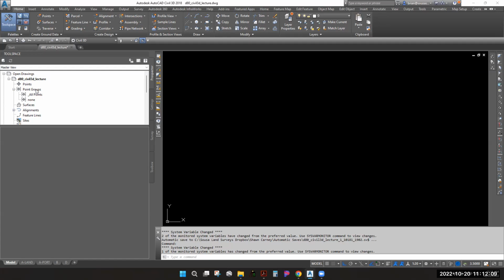Everybody makes mistakes. And so if we had to go out to a specific site and figure out maybe we had an error in one of our points or our setups, or maybe there was an error that occurred within the instrument, it's better to be able to identify which day we did than have to sift through thousands and thousands of points.